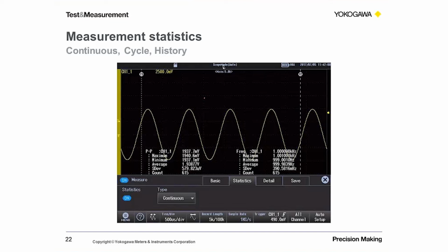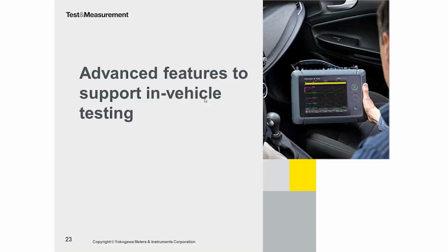We'll now move on a little bit to talk about how we are providing the products, particularly for supporting vehicle applications or railway applications. We were the first company to offer serial bus analysis on our digital oscilloscopes. Essentially, that enables the user to probe physical layers of buses like CAN, LIN, or even I2C or SPI, in order to look at the physical behavior of those buses.